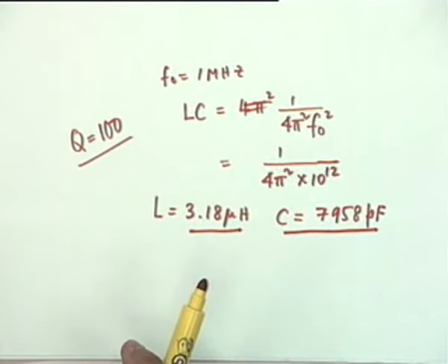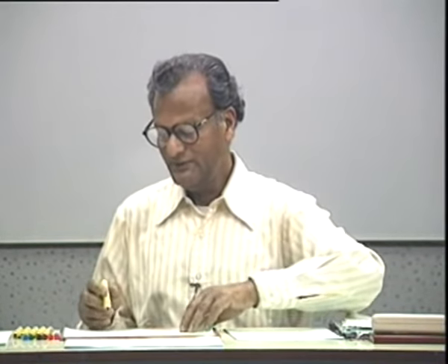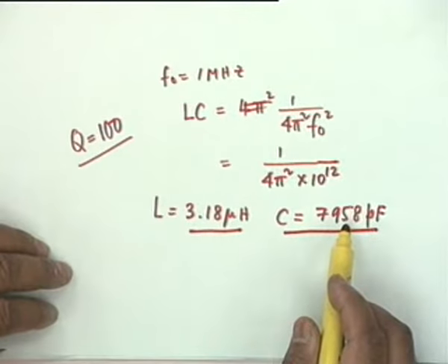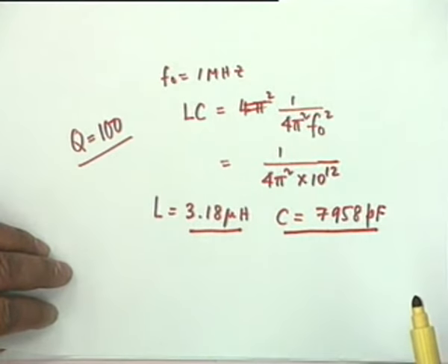The smaller the capacitor, the smaller is the size, and the better is its loss characteristics. Agreed? The higher the capacitor, the bigger is the loss. That is why electrolytic capacitors cannot be used in such circuits at all, because they have a very low resistance in parallel.